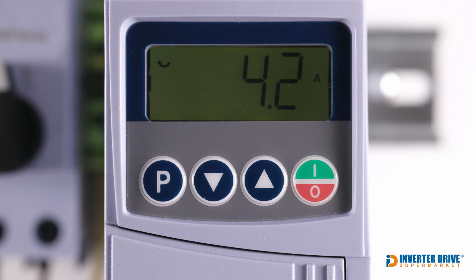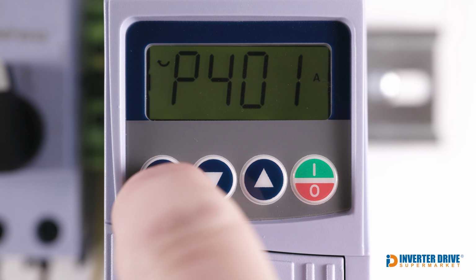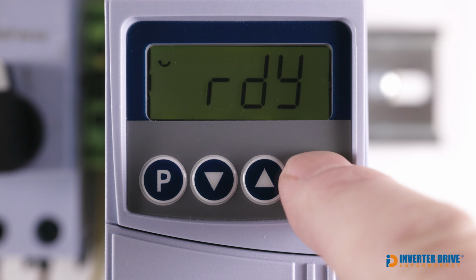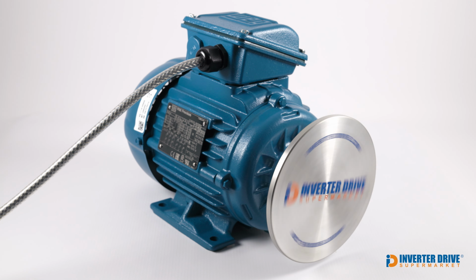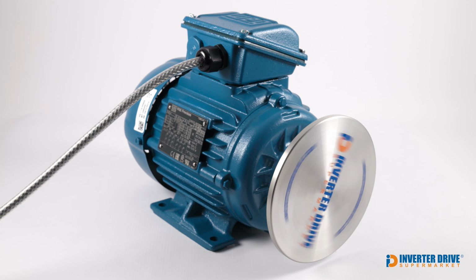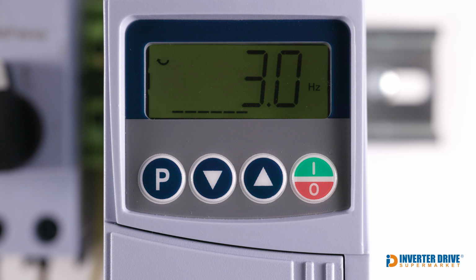In part 1 we performed some basic commissioning steps to match the inverter to the motor we're using. We also ran the motor to check and correct the direction of rotation. So to pick up where we left off, let's start the motor. The display automatically changes to show the value of parameter P002 so we can see the output speed. As before, the motor is running slowly, 3 Hz, which is the default.